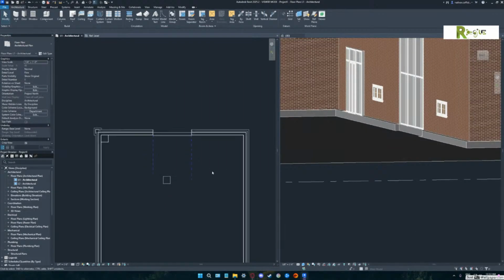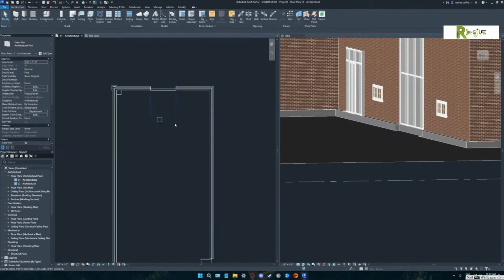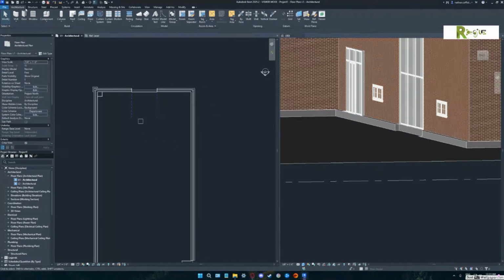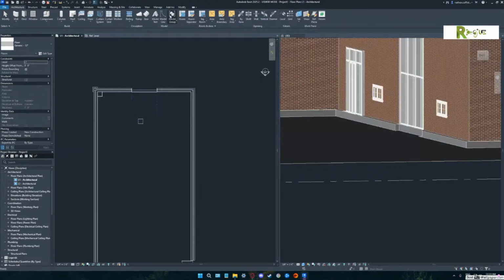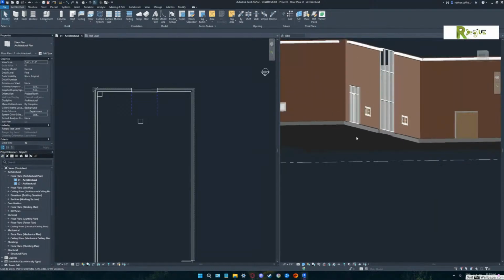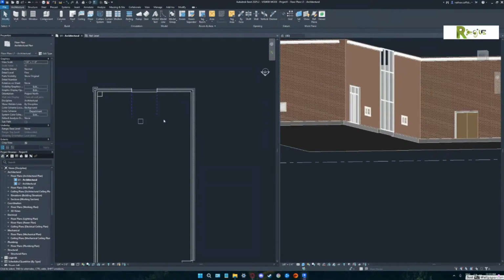What happened there is you were doing a new floor and you didn't draw anything, so it didn't pick anything up. Right. But it's going to ask you if you want to heal the walls or cut into the walls or whatever. Sometimes you get annoyed by that, but make sure you read that real quick, because it'll do two different things depending on how you answer that. Right.